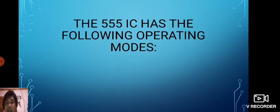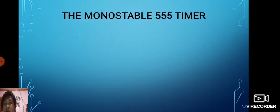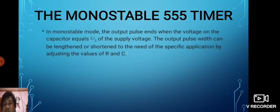The 555 IC has the following operating modes. The first mode is the monostable 555 timer. In the monostable mode, the output pulse ends when the voltage on the capacitor equals 2/3 of the supply voltage.